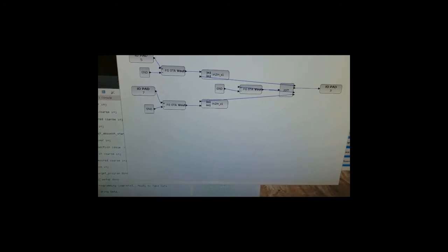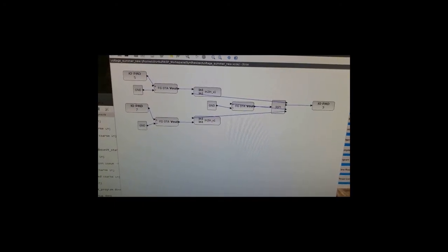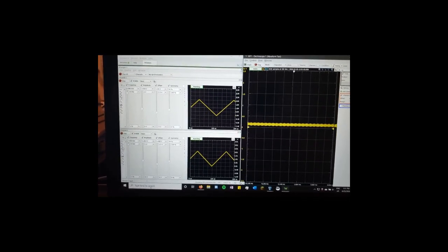In our testing, we were successfully able to sum two signals with all OTA bias currents set to 10 nanoamps. Future teams should expand on our design by testing with up to 12 input signals. These signals will represent the 12 notes in an octave. Different bias currents should also be tested to keep the resulting waveform within your design specifications.